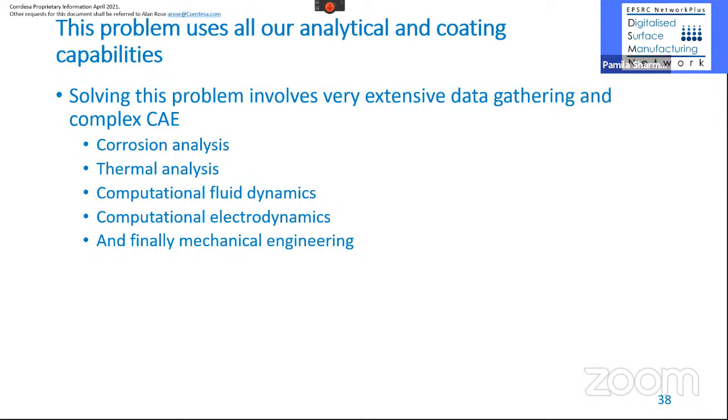Yes. There's a question from Peter Darnley, and it is, what is the optimal nickel content for a good zinc nickel coating? Oh, the optimal coating. Okay, yes. The optimal is about 15 weight percent nickel, which is about 16 atomic percent.